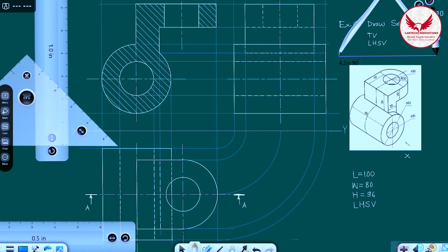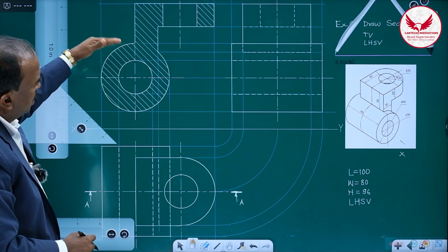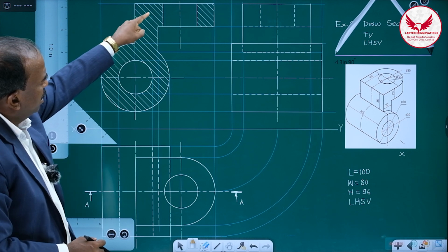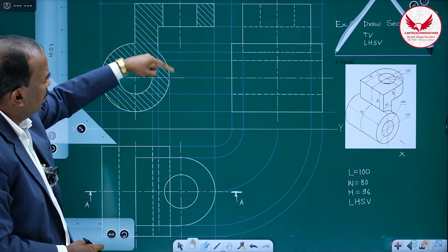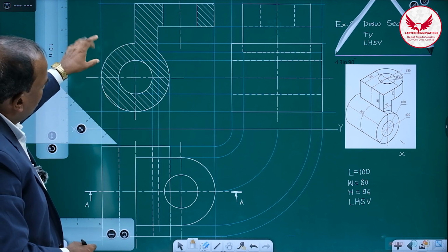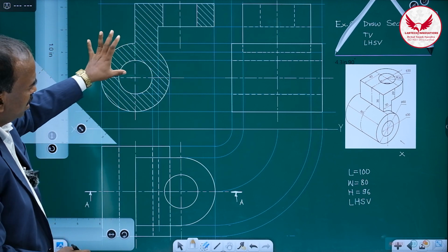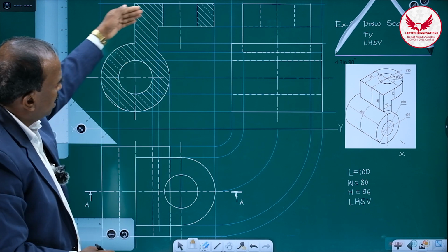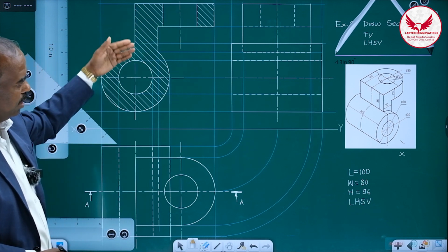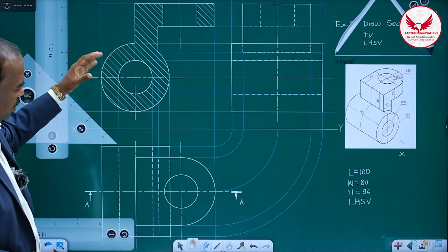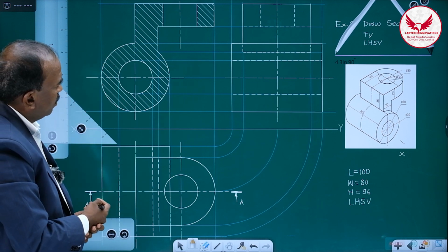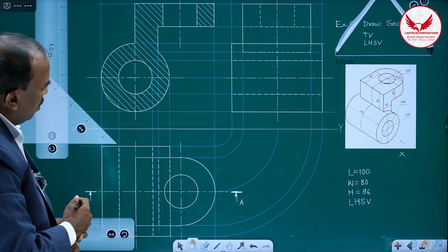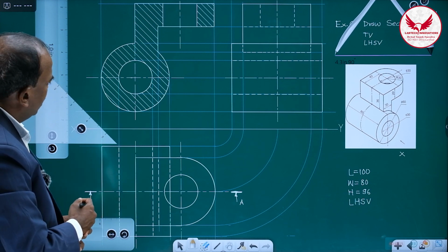So these are the section lines. Means this view is sectional view, and see that these hatching lines are accompanied by outer lines that are always dark. There will not be any dotted line in the sectional view, because this hatched portion is the most visible part, it's a new cut shiny surface. So keep this in your mind. Now apart from the dimensioning, everything is done.